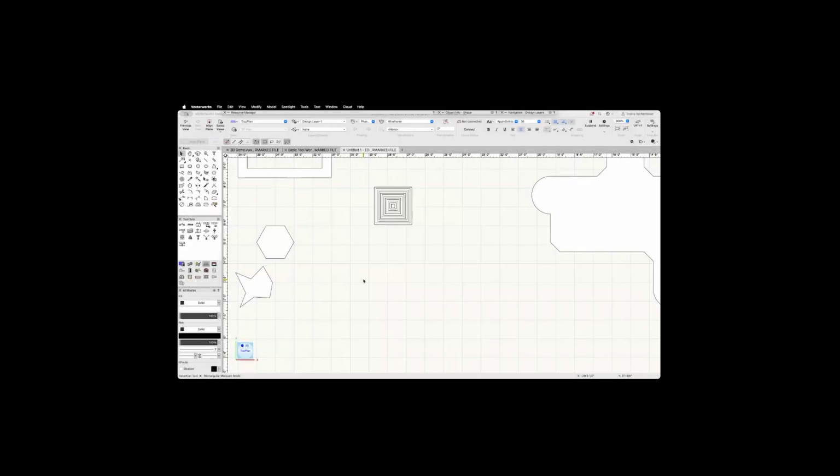The last tool that we're going to look at in this exercise is our Move by Points tool. So I'm going to start by just drawing another 2 foot square rectangle. So again, I'll activate my rectangle tool, number 4, and I will do this as 2 feet and 2 feet. Great, there's my new rectangle. I'll just move it down a little bit so it's out of the way. And now I'm going to move and duplicate these by a specific distance.